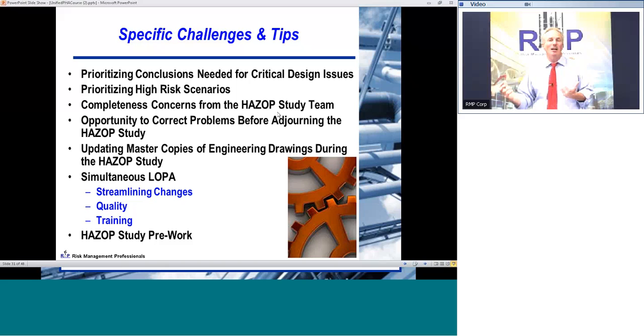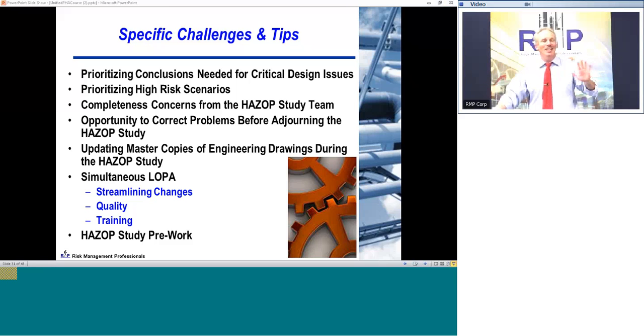The process engineer gets really excited about it, and very simple, obvious improvements to safety, they're more than willing to just, a lot of times with the modern tools that we've got, they'll have a copy of the P&ID on the screen, make the change on the spot, all the team sees it, they're happy with it, boom, the job's done. You've actually made the change very cost effectively, moved it forward, and you can do that by using this HAZOP framework. A lot of the current technologies associated with pulling all this information together, and the carrot of, gosh, getting the job done means that I can go home on time for a change.